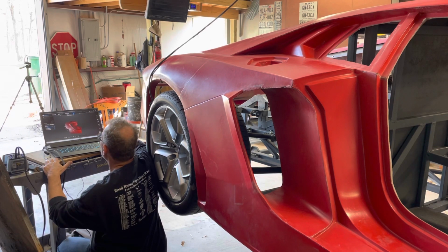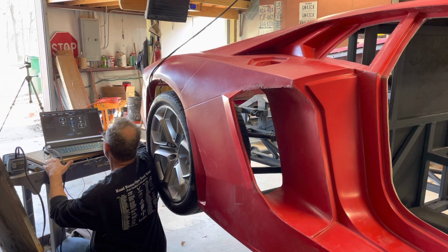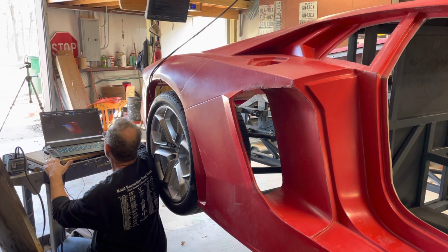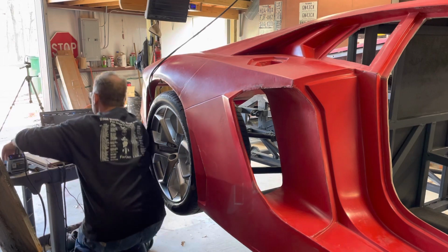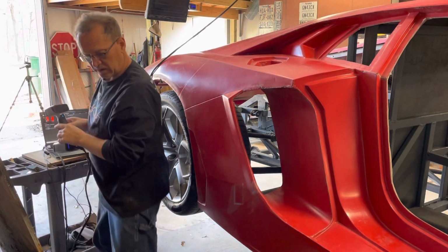All right, so I go over here to project group and I add another project group. And the project group is just a scan. So I'm picking texture scan, that's why it picks up the color. Pick features is how it's going to align. And then I found out that we can use low detail in this and it gets more than enough detail for what we need. So I'll click on apply, it creates my new project, and now I go through this process again.